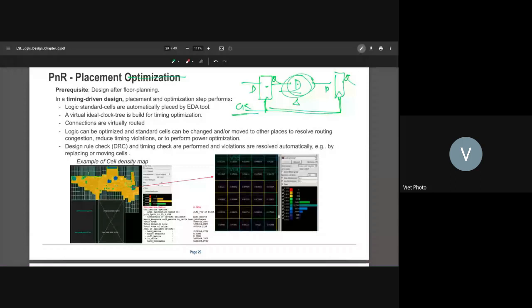Fine. But during the placement, we don't have any clock. We didn't do any routing yet. We just placed the cell. So that means there is no clock. In that case, we have to proceed with whatever we have. Then we have to assume that the clock is ideal, which means the arrival time at every flop's clock input will be 0. So in the placement, they just consider that the arrival time of the clock to every flop will be 0, which is perfectly, ideally synchronized. All right, so that's not a choice, but we have to assume that, so that it's better than nothing. We need to have something to refer to, so we have to do that step. When we proceed, we have more information, then we'll update our data, right?